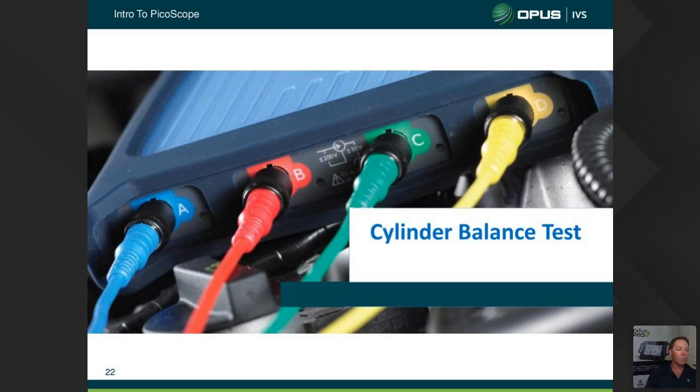Now, what can happen if you're pulling injector harnesses off the injectors while the engine's running, and you do it on a piezo diesel, you run the risk of popping that injector harness off while the injector's open. Now, no spring in the world will collapse that piezo stack once you remove current. The only way to collapse that piezo stack is to run the current through that injector in the opposite way. Now, the bad thing is if you've got the engine running and we pop that off, well, we'll dump all fuel pressure into that cylinder, which means the rail pressure will drop, the engine will flame out. You can run the risk of, if the cylinder's hot and we pop that wide open, we can put a hole in the piston. So be very, very careful doing it that way.